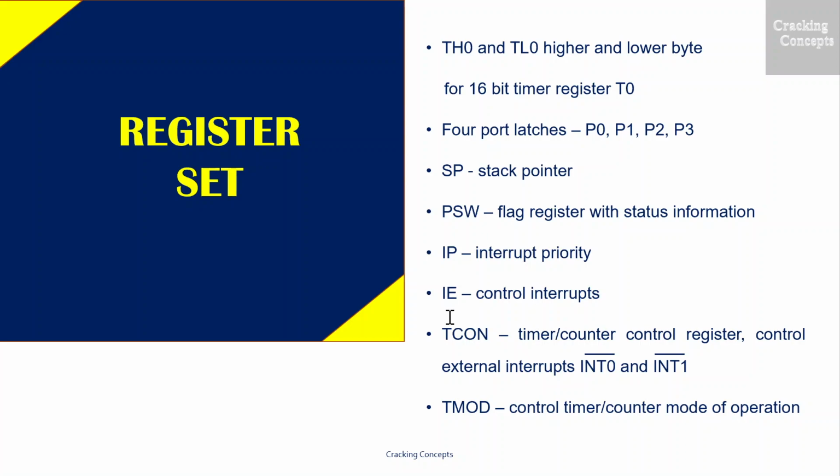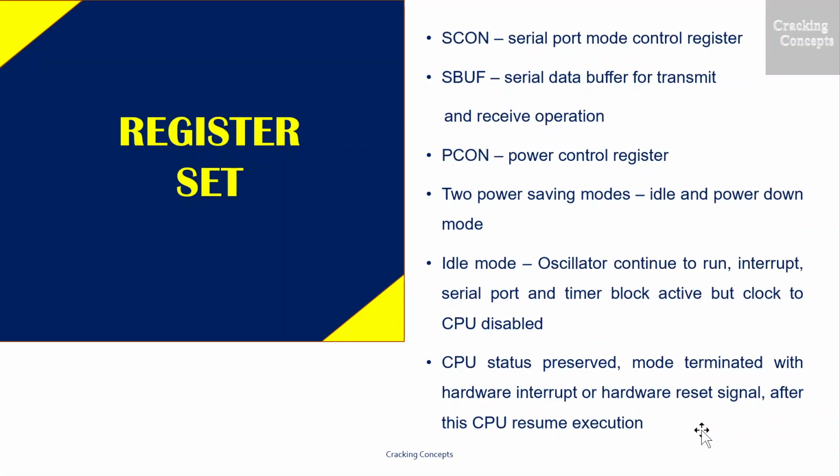TCON is called timer or counter control register. Some of the bits of this register are used to turn the timers on and off. This register also contains interrupt control flags for external interrupts INT0 and INT1. The register TMOD is used for programming the modes of operation of timers or counters. SCON register is a serial port mode control register and is used to control the operation of serial port. The SBUF register acts as a serial data buffer for transmit and receive operation.